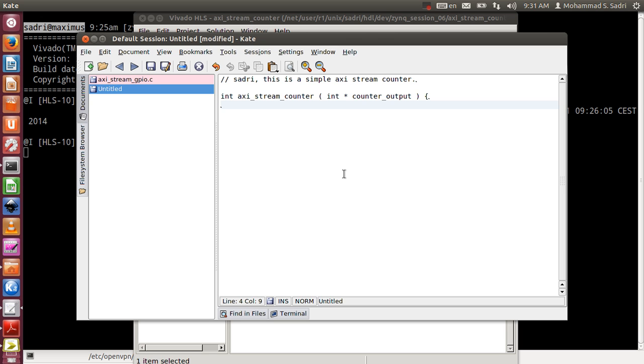And then inside the module, obviously I need the registers which are counting themselves. So I would say static int counter value, and it should be defined as static, and it's better for me to also initialize this in the beginning to a fixed predefined value.